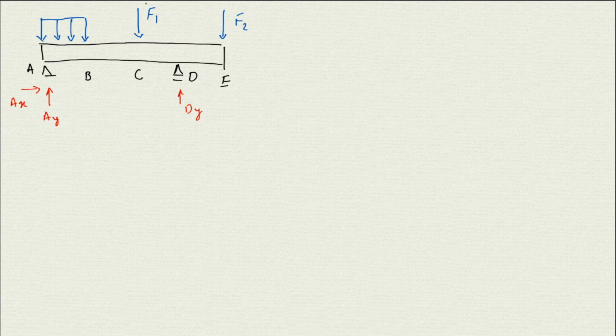Then between F1 and DY, because there are two sets here, we need to have another section. And between DY and F2 we also have to have another section. So between every two single forces, we need to have a section. Also, if we have a distributed load, we need to have one section in that distributed load as well. So I'm going to start with that.